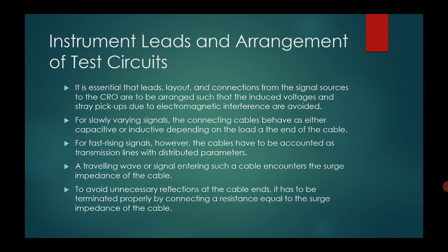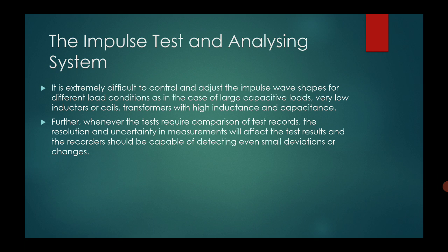To avoid unnecessary reflections at the cable end, it has to be terminated properly by connecting a resistance equal to the surge impedance of the cable.